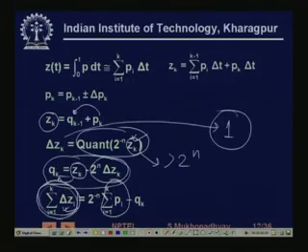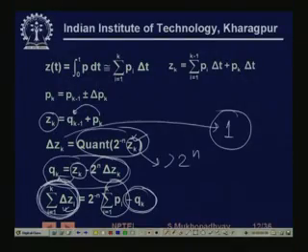We are sending delta zi, but delta zi are actually related to delta pi, because this is nothing but this minus qk, because every time the rest of the value is stored in qk, so whatever is remaining is stored in qk. So actually this number which is being sent to the motion control system and the true integral can only differ by maximum by the length of qk, and so the difference is always bounded.